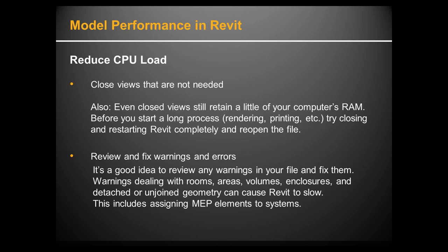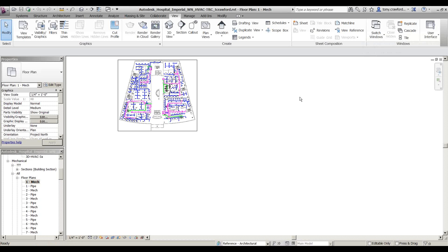and then do the long process. Yeah, and that's something really to remember and point out, and I stress this a lot in class: have a good way of naming everything in Revit, naming your views especially. The reason being, and I think it ties directly to the memory issue, is that every time you open up a new view in Revit, it sequentially numbers it. So if I do section, it's section 1, 2, 3, 4, 5. At the course of the project, you're going to have 50 sections in that project.